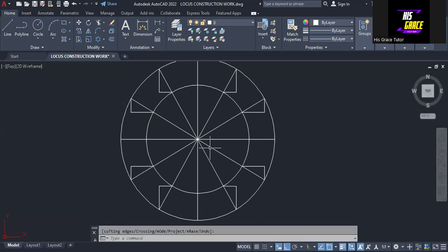So the next that we are going to do is that we come to draw and we select spline fit. So this particular tool, then we start from here. But before we do that, we have to disable auto mode. So I've disabled the auto mode. Then I will select the spline fit again. So coming to this point.